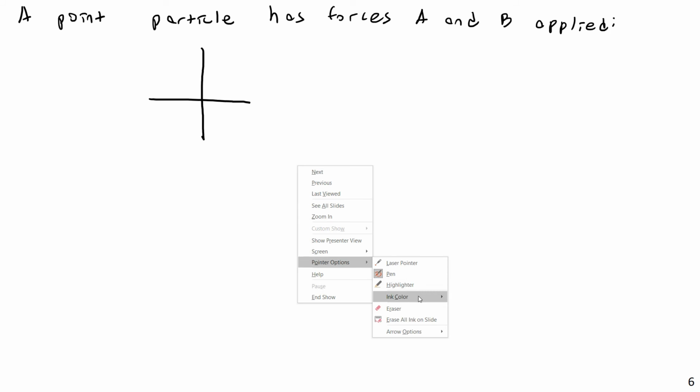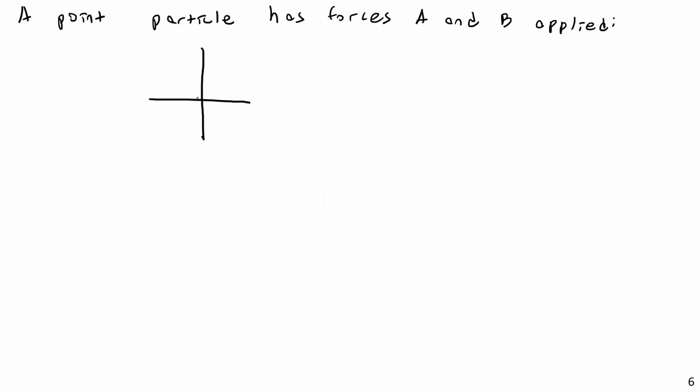Let's say I set up a system where there is a 10 Newton force at an angle of 30 degrees, and a 20 Newton force at an unknown theta. Find theta. So we're told that we have 10 newtons at an angle of 30 degrees above the negative x-axis and 20 newtons at some unknown theta.